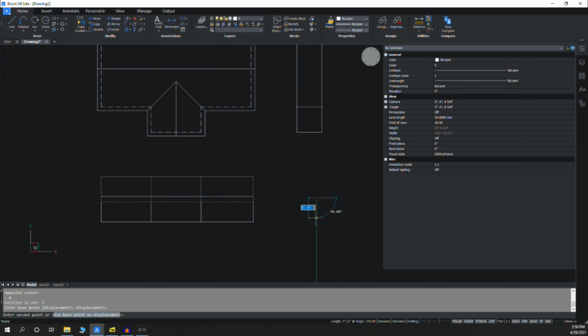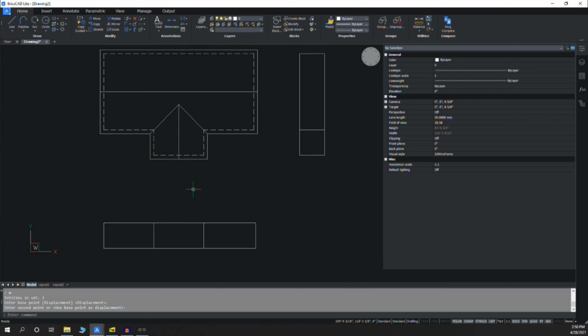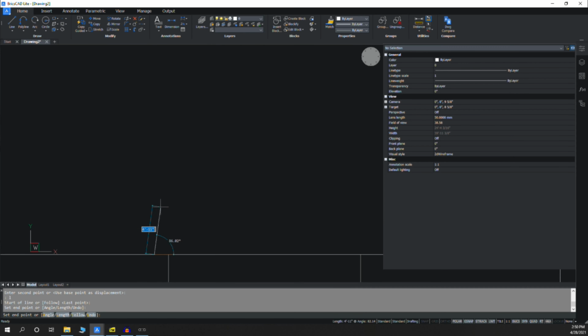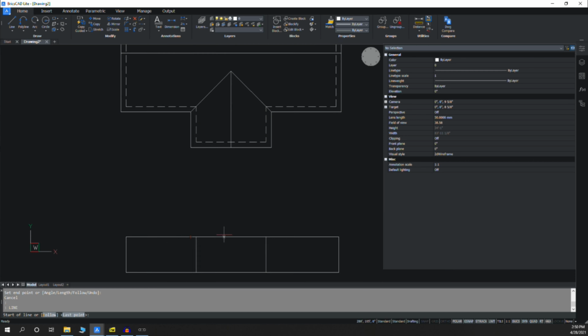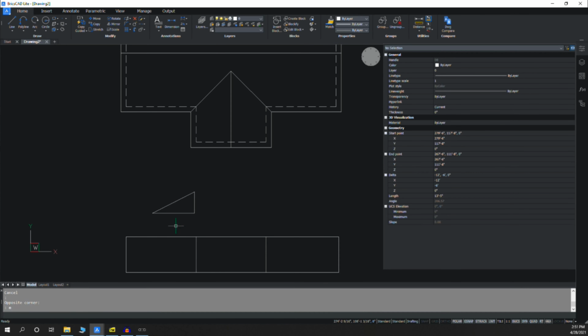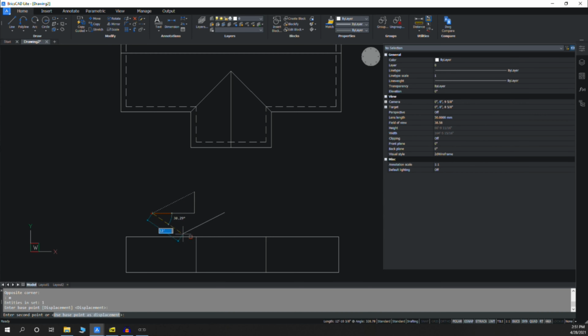Now let's draw the roof in an elevation. So again, we wanted an 18-inch eave, so I'm going to come 18 inches off this line. And that gives us a point over here. It's kind of invisible because the lines are laying over each other, but you can see it if you have your snaps on. So to get that 6/12 pitch, we're going to go over 12 feet. We're going to go up 6 feet, and I'm just doing this off to the side so I can get this line here. That's the right pitch. I don't care about the length or anything like that.